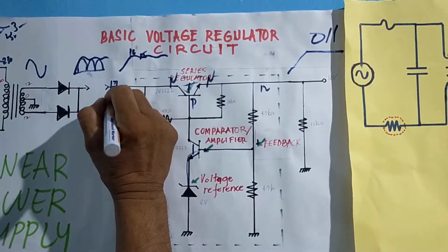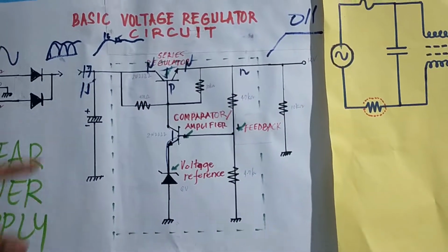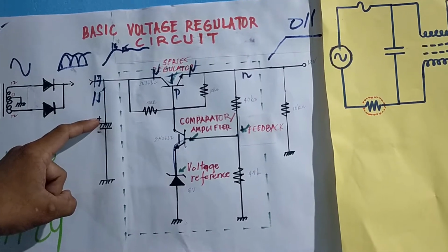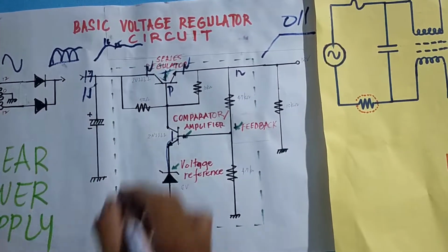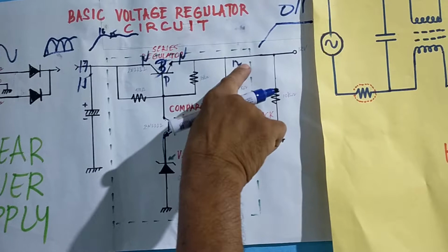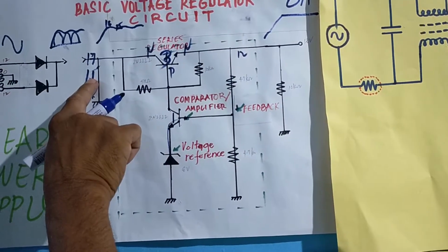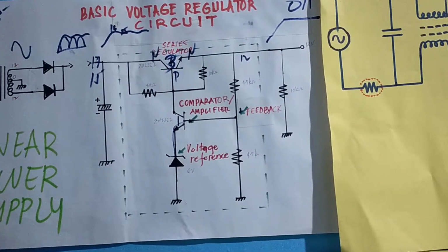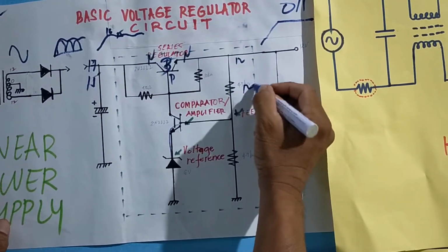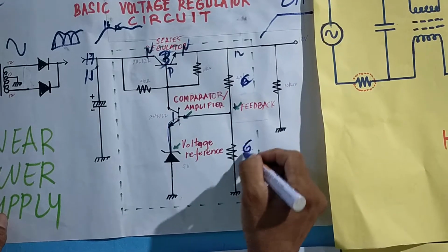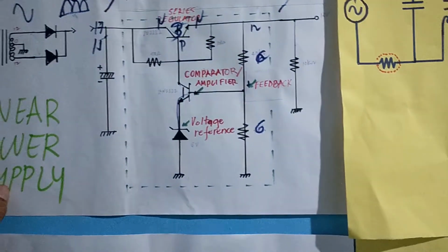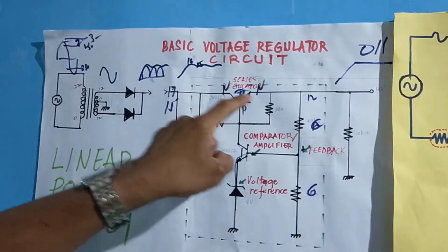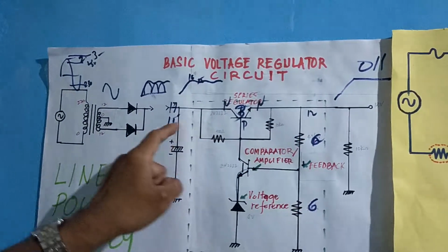But when the voltage is decreased, from 17 to 15, the voltage here should be 3 volts, because 12 plus 3 is 15. In what way does it become 3? Because it goes like this, class. This should be 12, this should be 6 volts, this should be 6 volts. And this is 3 volts, making it 15 volts. 3 plus 6, 9 plus 6, 15.